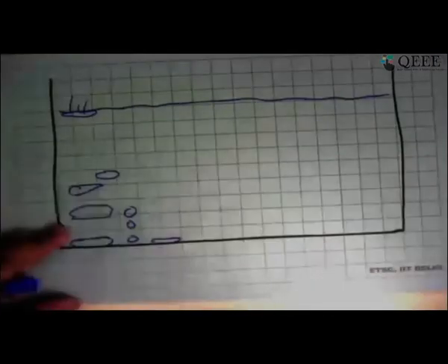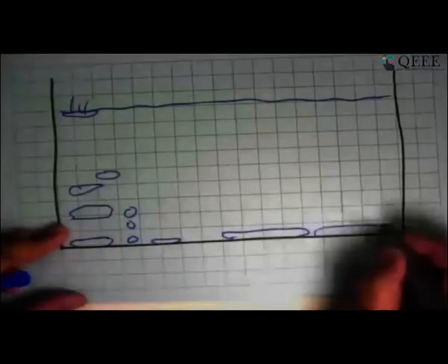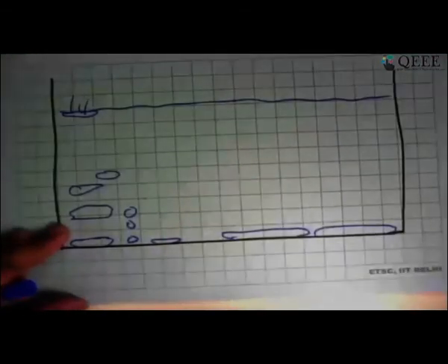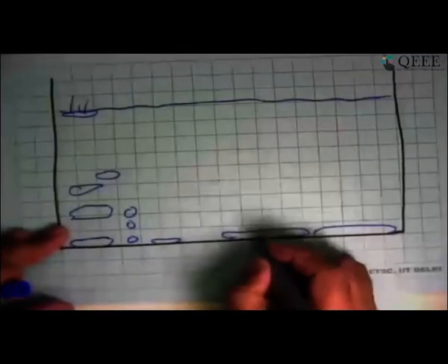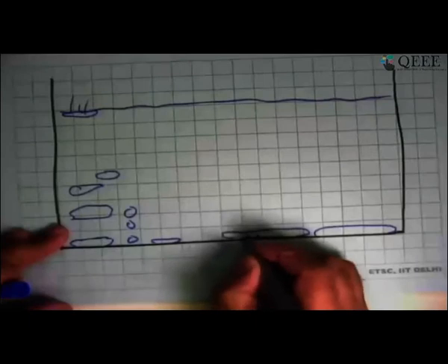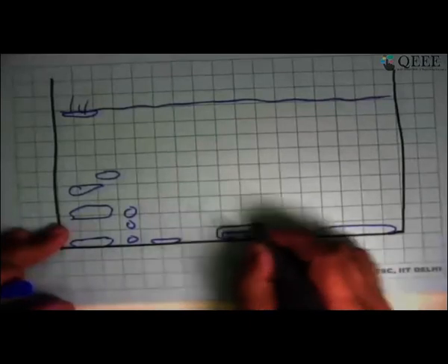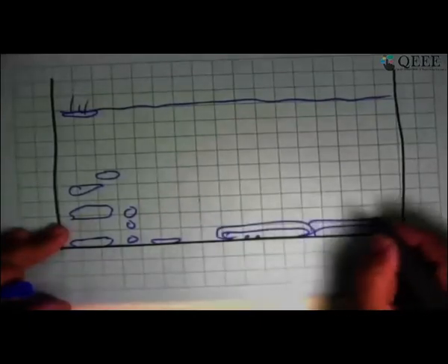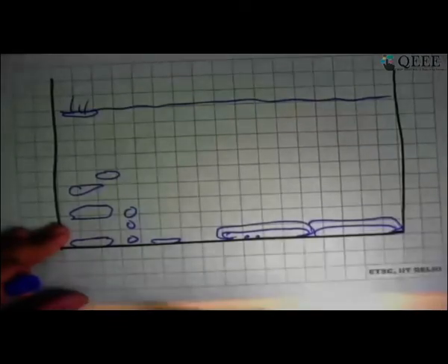As the wall temperature increases further and further, more and more of this wall begins to get blanketed with vapor. This vapor is formed very quickly. It rises up. Another liquid comes there somewhere. Again, it immediately forms a bubble, vapor, film, and it grows up. And maybe these two join up and form a bigger one.